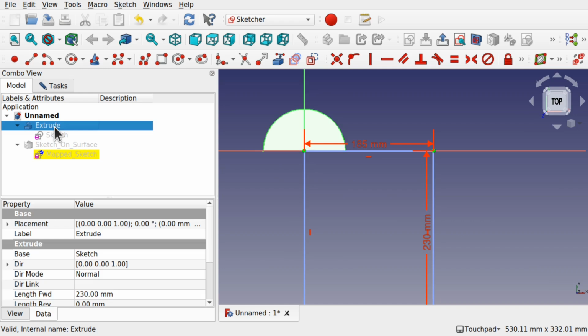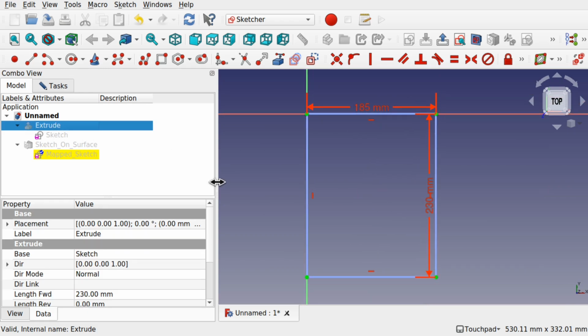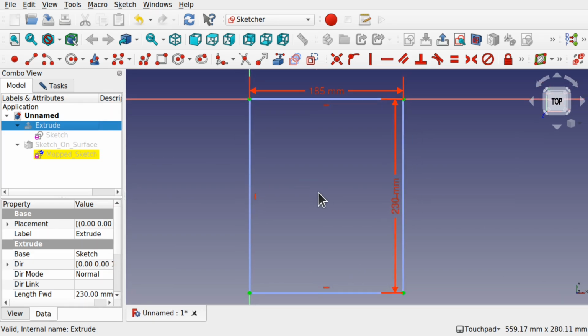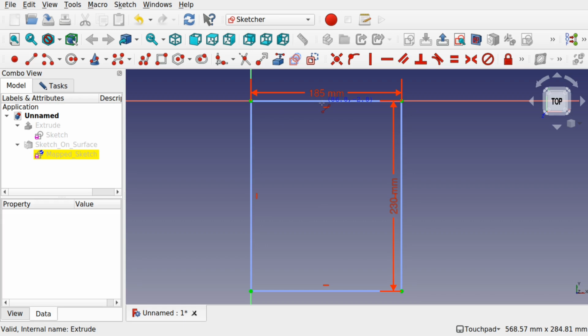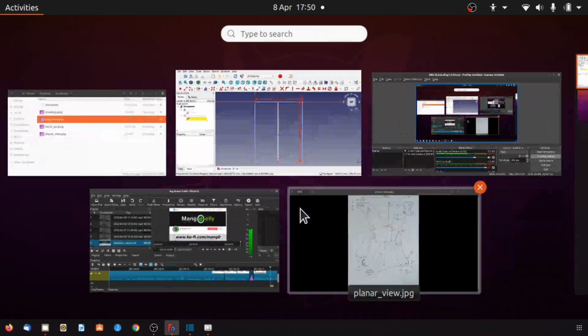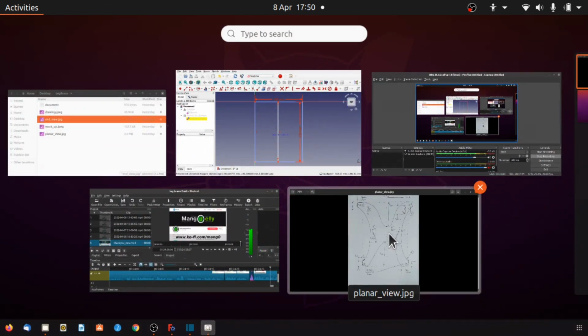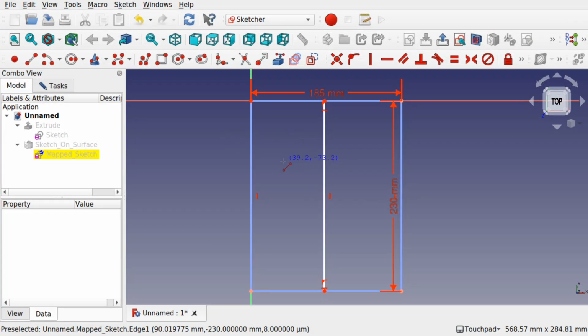Let's just hide the extrude. Now we can start sketching in this. Let's just shrink this down a bit and bring this out. So we're going to get our base in there. We're going to put a line of construction geometry along here, and looking at this, I'm going to put 2 lines for where this curve is, because we can make this curve tangent to a line that runs along here, and we've got some dimensions here of 5 centimeters.